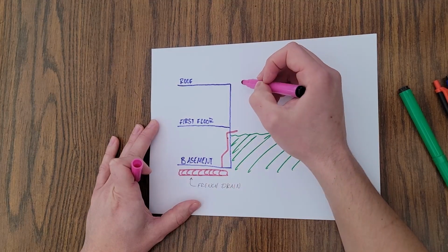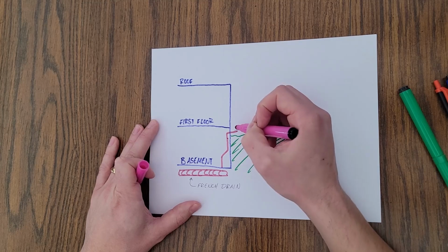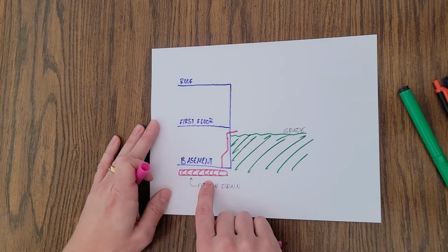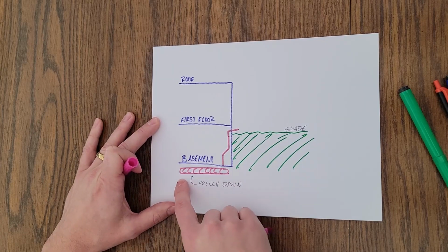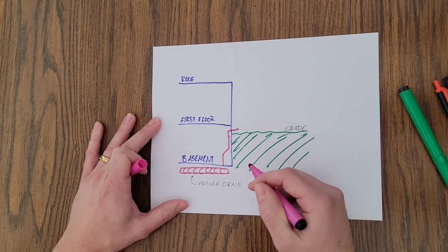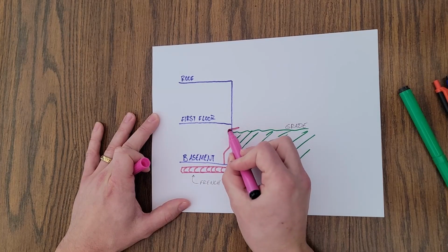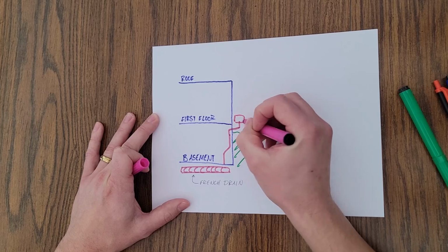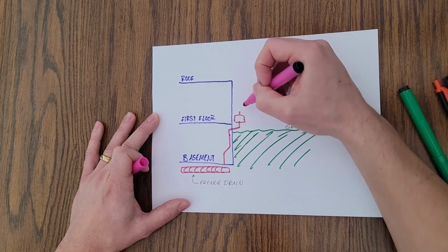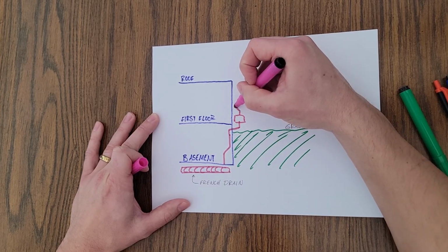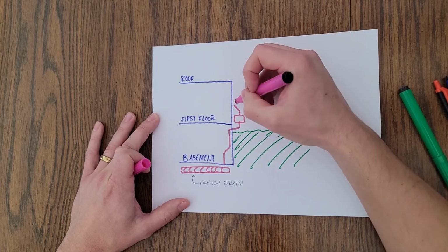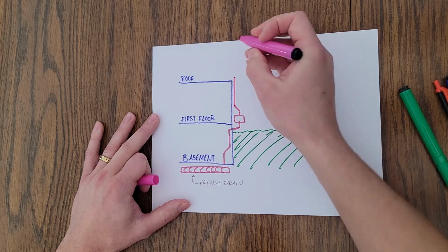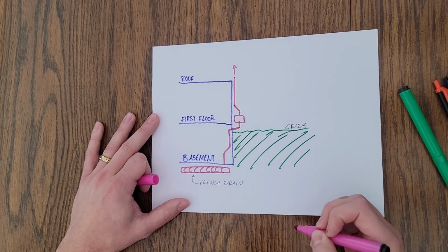Because when it rains or when precipitation forms inside of your radon piping, you want it to all drain back towards your French drain, which then drains to the sump pit, so your sump pit can then discharge it outside of your home. So we're going to 90 through the exterior wall, we're going to 90 up towards our fan, and then we're going to come up past our fan, 45-degree angle back up towards the house, and then another 45-degree angle to go up along the house and then to discharge above the roof.